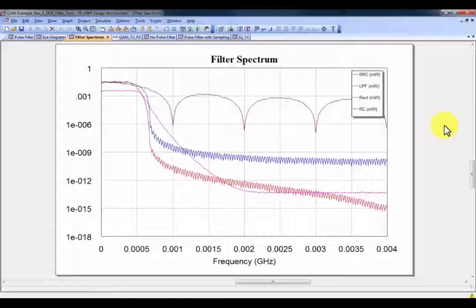And so we want to attach some filters in order to limit the bandwidth. I'm going to look at 3 different types of filters. One is a low-pass filter, and that's shown here in the pink. You can see it's a standard flat response, and then it tapers off so that it filters out just the higher frequencies. And this may be just a simple multipole low-pass filter.